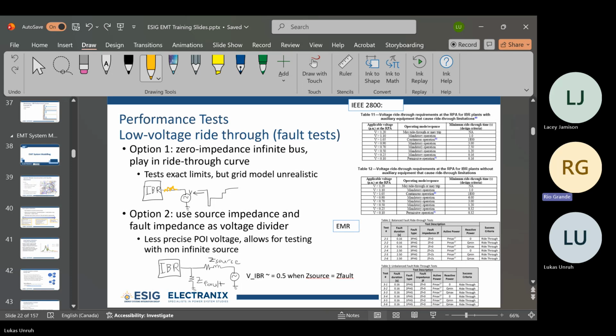That's another benefit of doing it in the simulation domain, because a lot of times people forget to turn the protection back on. There are a lot of models out there with commented out frequency protection settings, or plants interconnected last year with the PFR loop disabled because they turned them off.